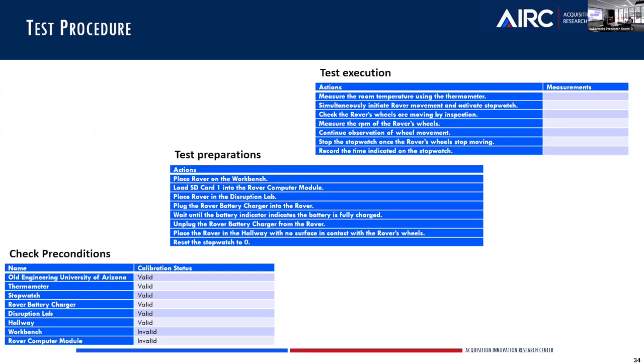We did some analysis to look at how changing the tire dimensions may change the outcomes as well. You could think of this as an earlier one that we did with the tires. If you change the dimensions of the tires, let's just say you double the tires, you can go over rocky terrain, right? But it's going to decrease the mission life. If you do smaller tires, it can increase, but it can't go over this rocky terrain.